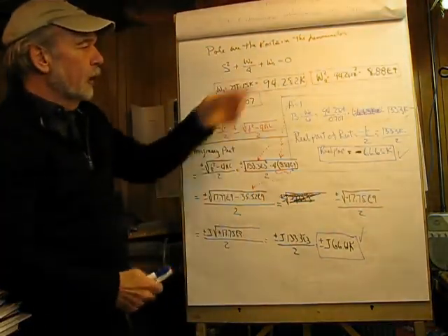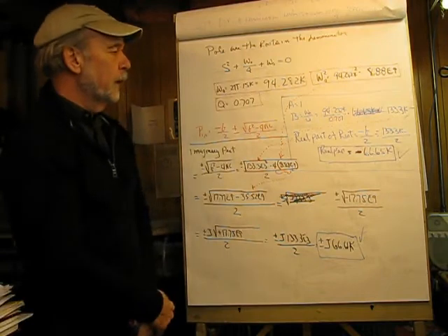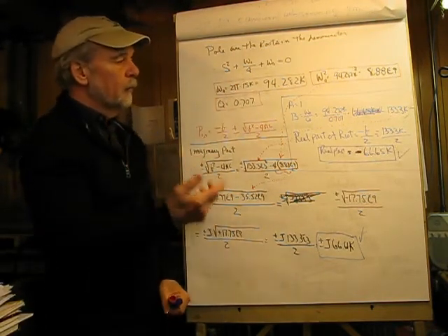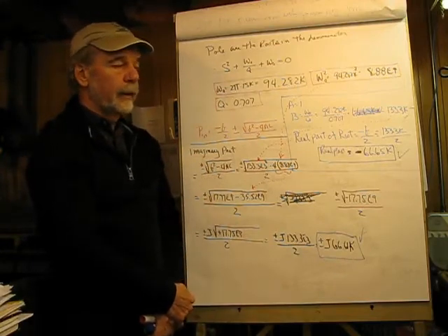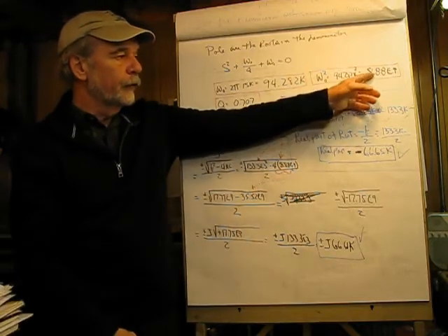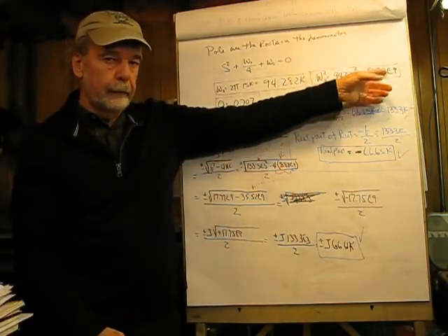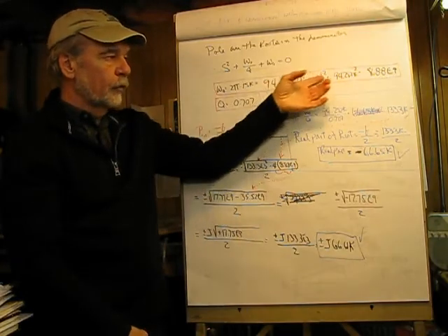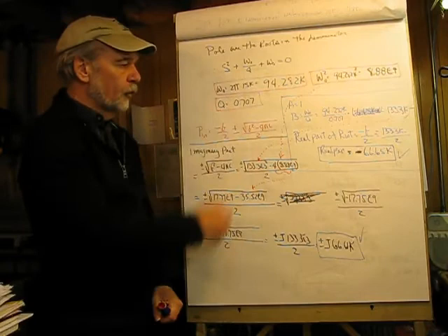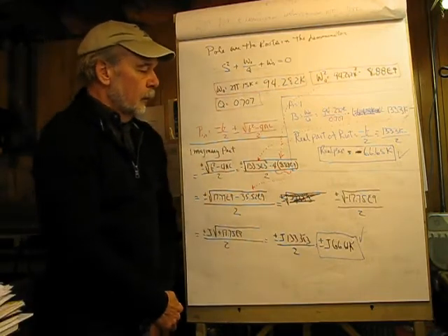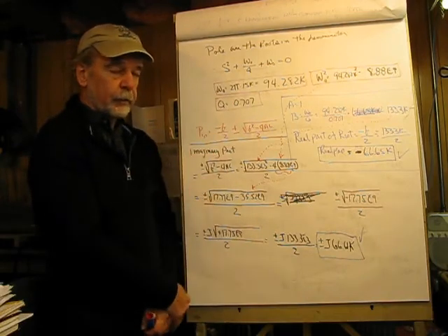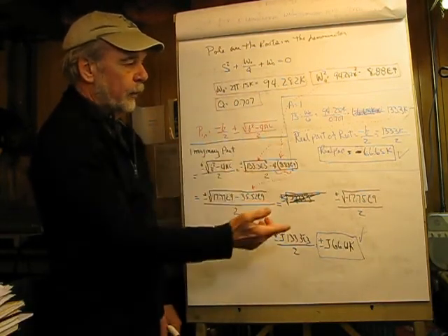So here's our setup here, setting them equal to 0, and omega 0, using 15 kilohertz as our corner frequency, comes out to be 94.282 k rads per second, and omega 0 squared is 8.88 e to the 9th. Now the reason I'm doing this up here is I'm going to need them later, so I'm figuring them out of the way. Q is equal to 7.07. So we're starting out with our equation here. Important to remember this is negative b. A equals 1 as said before.